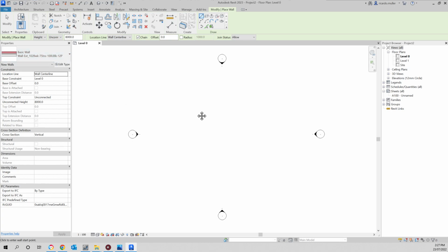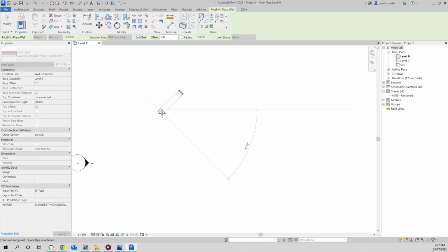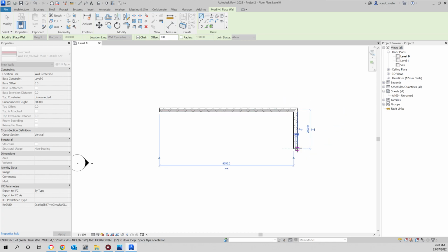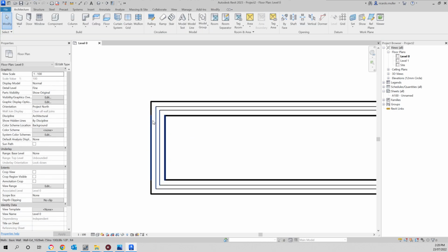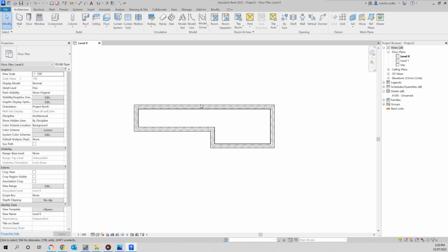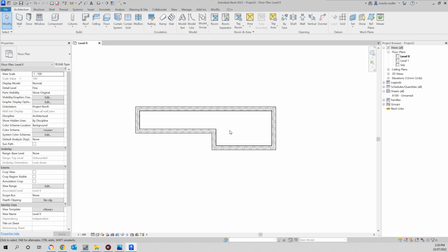Okay, finally we'll jump into the modeling environment window here, and we can click to indicate where we're starting the wall, and then a second click will tell us how far that wall goes. So here you can see I'm just clicking around and it's chaining all of these walls together. I can come back here to the start and just click, and it'll snap that wall back to the starting point. And there we go. We form an enclosure, right?